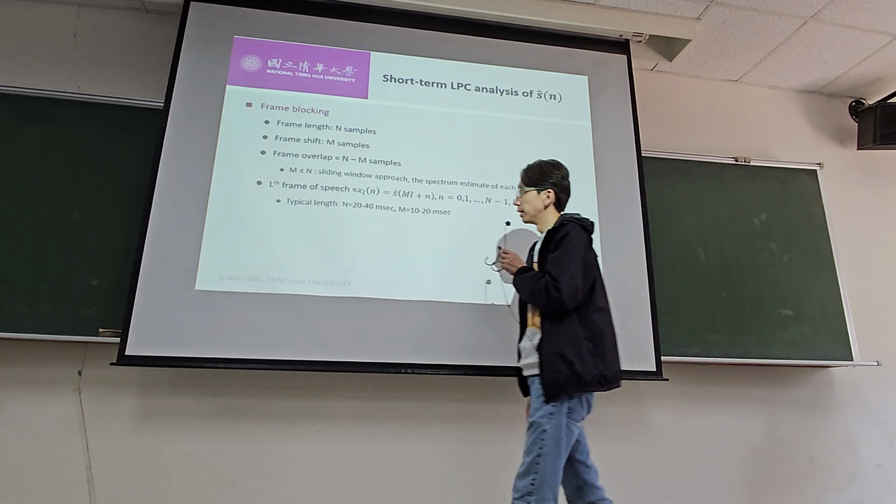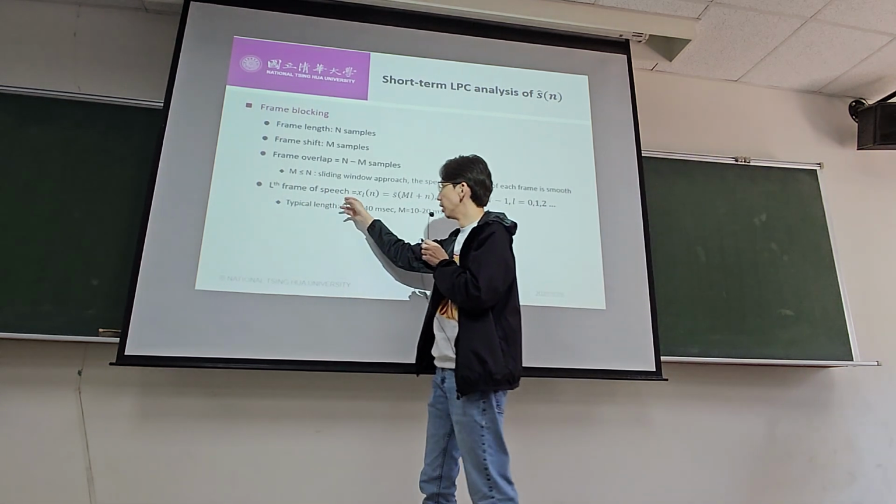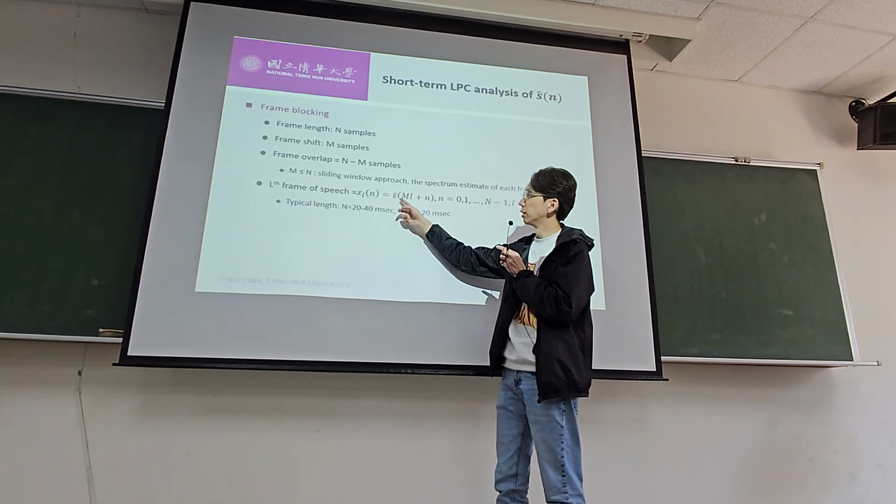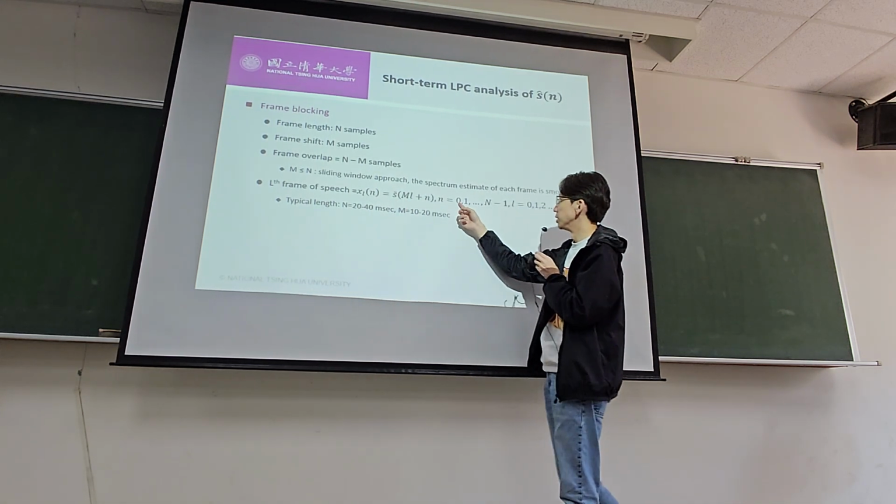So you can write the lth frame of the speech as x sub l of n, which equals the original speech signal x of m l plus n, for n from 0 to n minus 1.